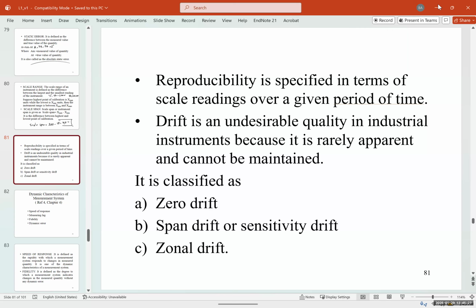One example of this that I gave you already was the ultrasonic sensor. Do you remember I talked about the ultrasonic obstacle sensor that you have on your car? The problem with these sensors is that if you measure a distance in the winter, it's going to be different from summer. If you do it in Amarillo, it's going to be different than if you do it in DC or in Houston. Because these measurement tools depend on the environment. Environment has a lot of impact on them: temperature, humidity, even altitude, so air density, all of that. And sometimes that causes a problem.